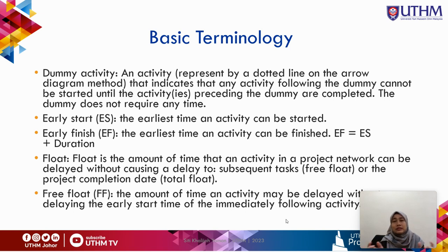This will enable that particular activity to delay its start a little bit without affecting the successor activity. And then you have the free float. This is the amount of time an activity can be delayed without delaying the early start time of its successor. This is what I told you just now.